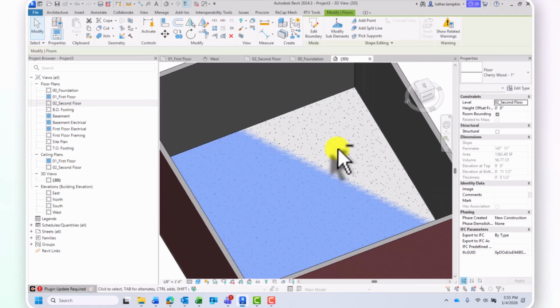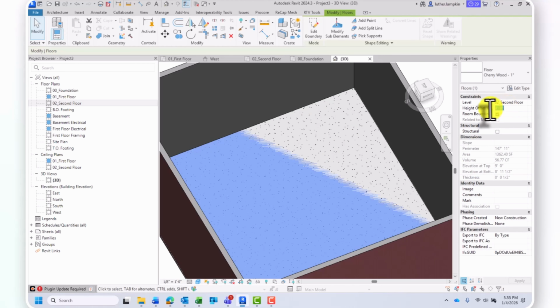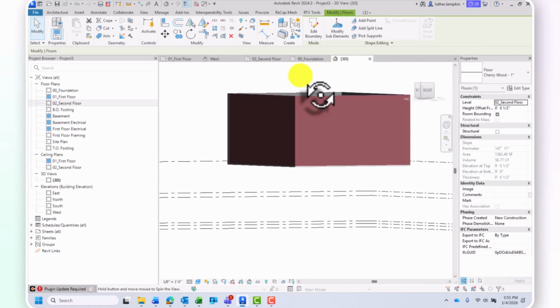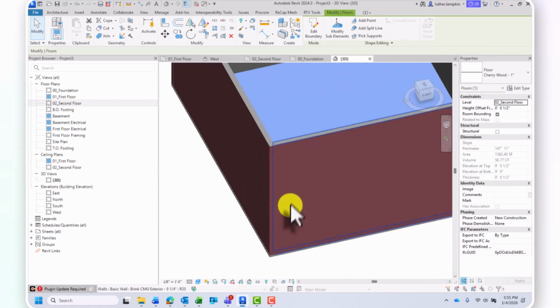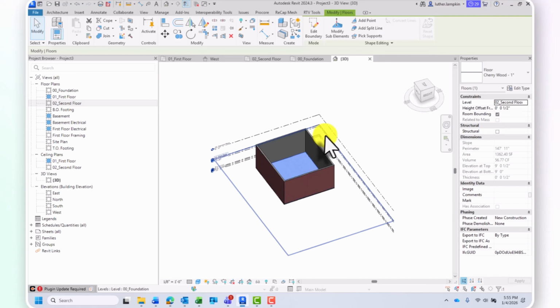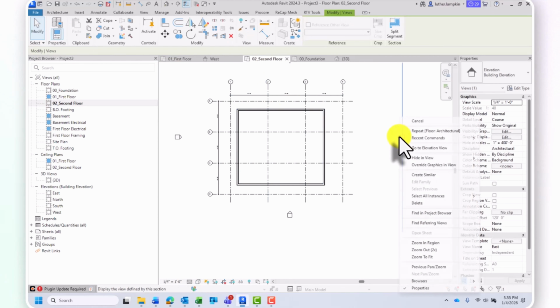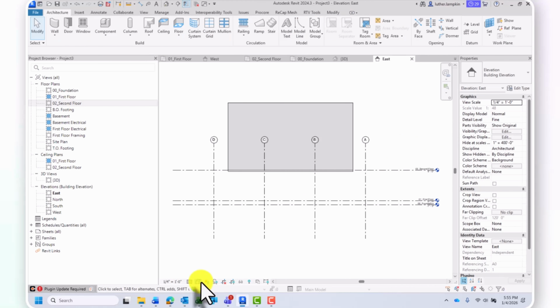All right, but one thing you may see is reflective. Why? Because I didn't account for this. Make sure when you put that on, the slab says 1 inch. All right, so now you have to give it a positive offset. Now you see it right above it. If I didn't, then it's still in the slab, right? All right, cool. So it's just important for you guys to understand that, because if I go back to the floor plan and go to view, let me show you, let's see here.